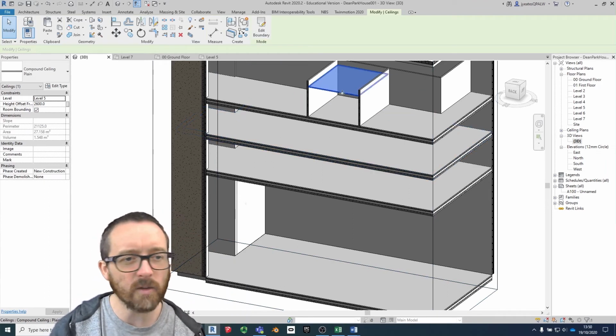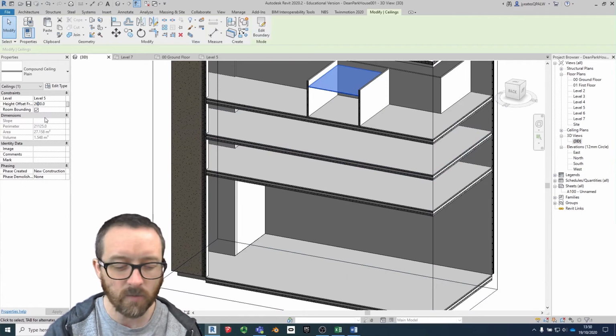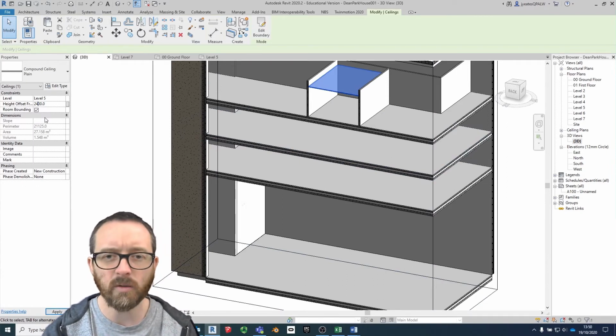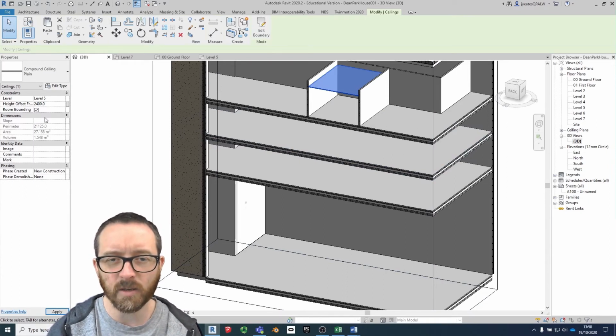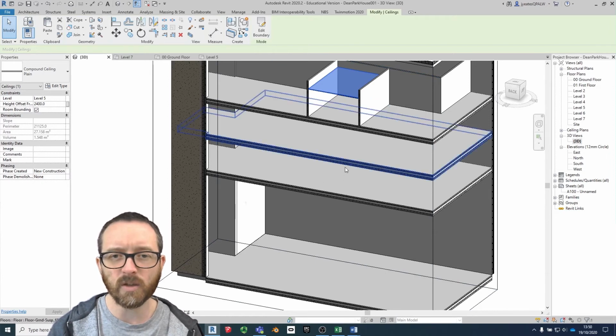and you can see there is my ceiling in this room here. Now ceilings, you can offset the height, you can change the height of this. I'm going to take off 200 mil, and you should see the ceiling move. When I move my cursor into the viewport, you can see the ceiling moved slightly there. Okay, so we can adjust those ceilings.